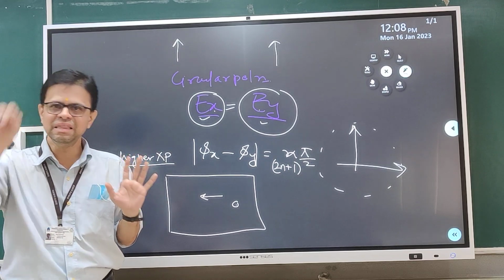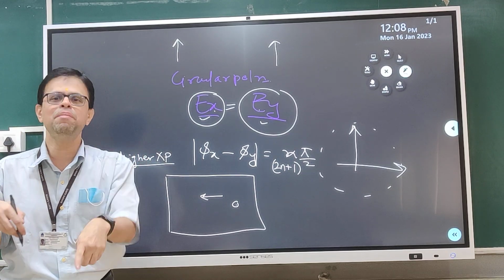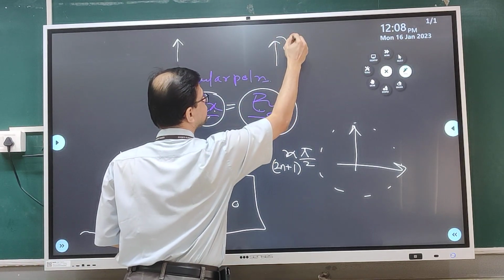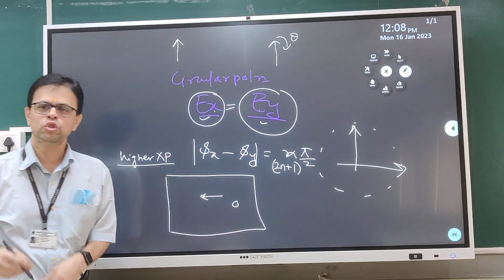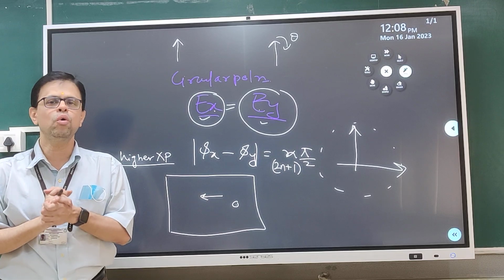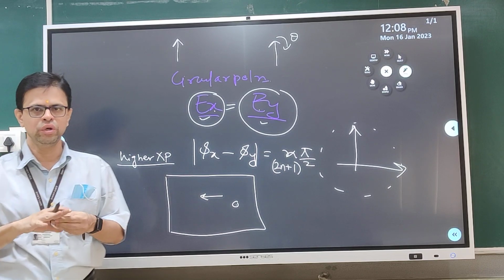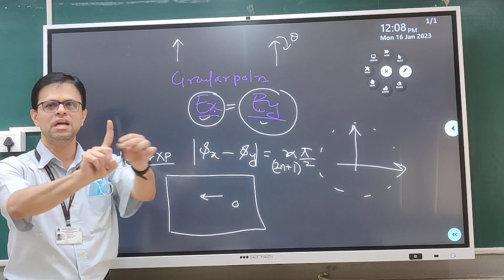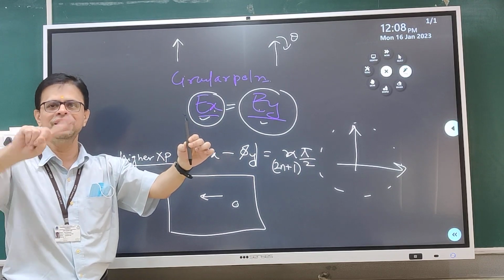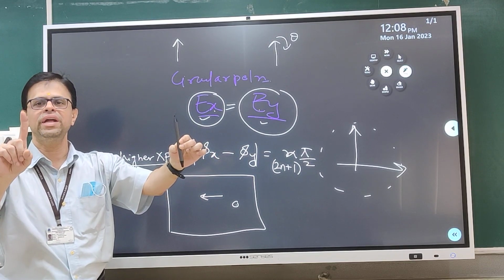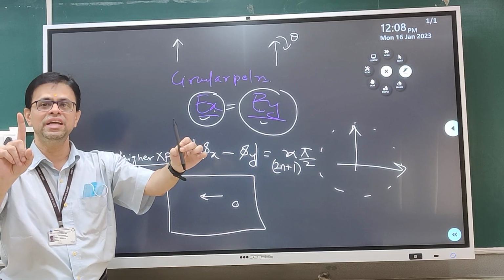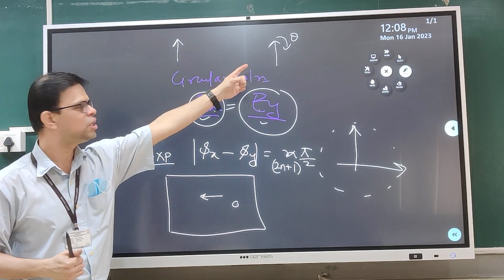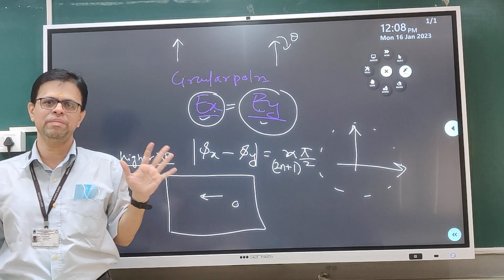After that, in the theta plane, which is the E plane of the antenna, we rotate this antenna so that you measure the copolarization component. So here, if this is my transmitter and this is my receiver, the two planes are matched. I am not rotating it like this, because that is going to rotate the antenna in the phi direction or orthogonal. So I am rotating it in this direction